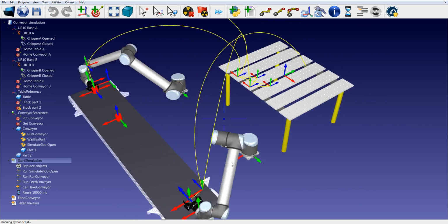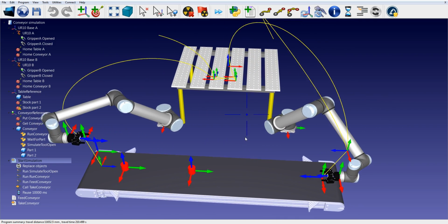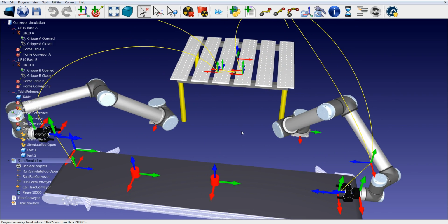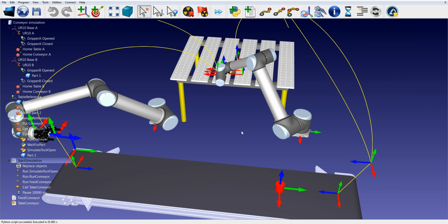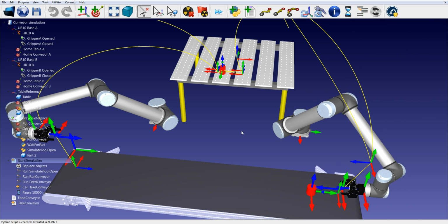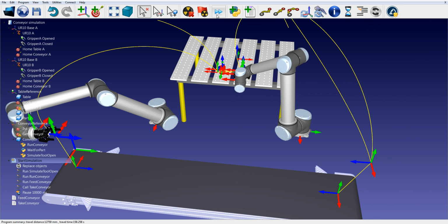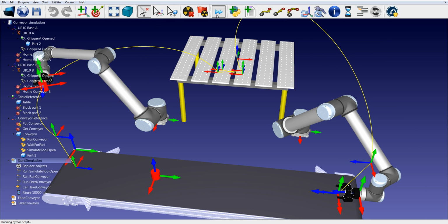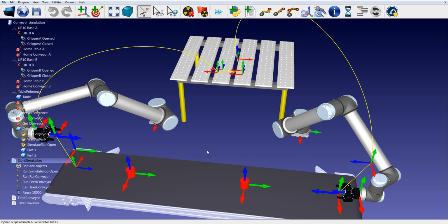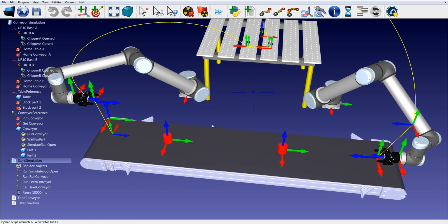After watching this video, you'll be able to build the conveyor sample station. We can double-click the Start Simulation program to see the final result. As we can see, there are 2 universal robots with the RobotiQ gripper. One robot feeds the conveyor and the other robot takes the parts from the conveyor. We can use the spacebar to accelerate the simulation. We can also press the escape key to stop the simulation.